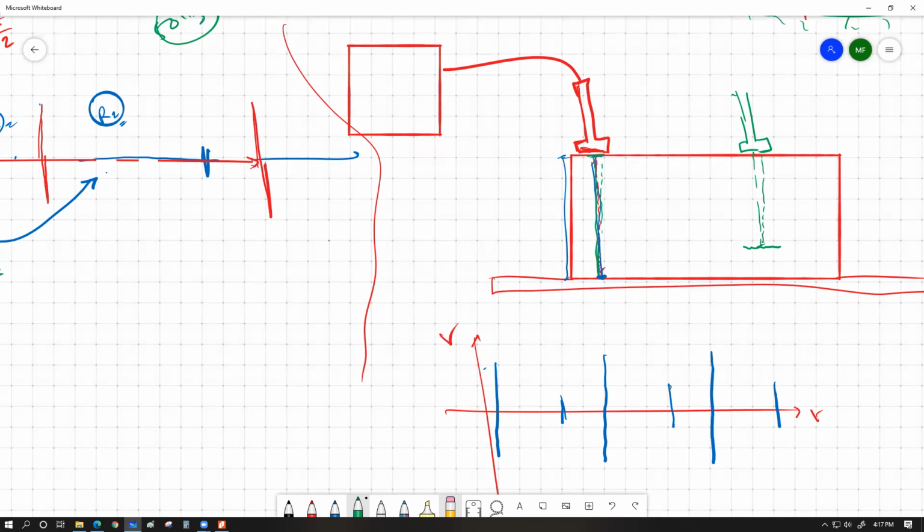The time it takes for the ultrasound pulse to travel a shorter distance and eventually come back would be smaller. This means if you do have a crack anywhere within this metal block, other than the regular reflected pulses obtained for most of the part, you're going to suddenly have, for one location, a much closer reflection, and that closer reflection should be larger in size because it's going to have a little bit more amplitude because it did not travel as much medium.